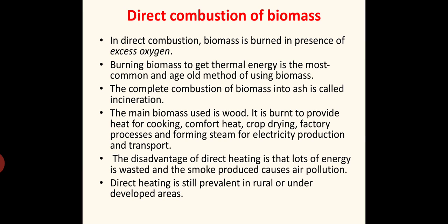Directly we are burning the biomass in the presence of oxygen, or excess oxygen is available. Why we stress that excess oxygen term is, in some processes we are not using oxygen for the combustion. That's why we are stressing that term. Burning biomass to get thermal energy is the most common and age-old method of using biomass. The complete combustion of the biomass into ash is called incineration. If complete combustion takes place, then we will simply call it incineration. And nowadays, high quality incinerators with high efficiency are available in the market for complete combustion.